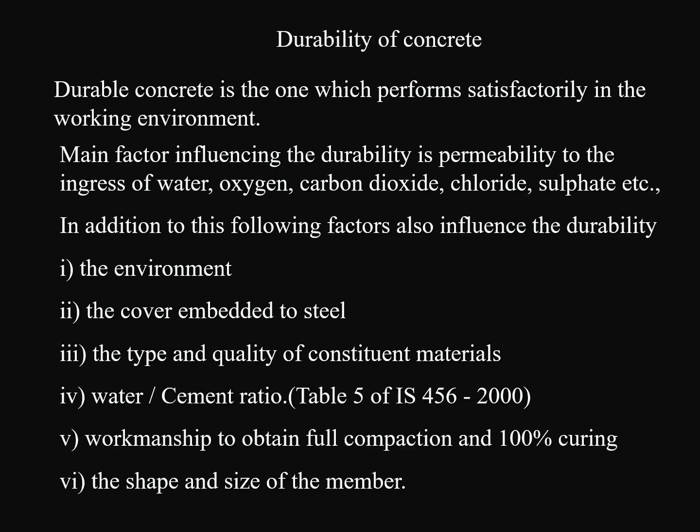Durability of concrete. Durable concrete is the one which performs satisfactorily in the working environment. Main factors influencing the durability is permeability to the ingress of water, oxygen, carbon dioxide, chloride, sulfate, etc. In addition to this, following factors also influence the durability.